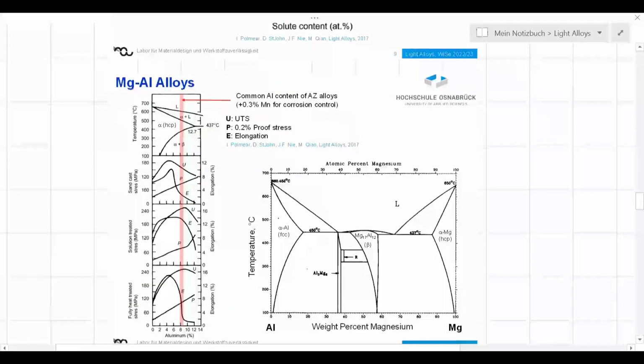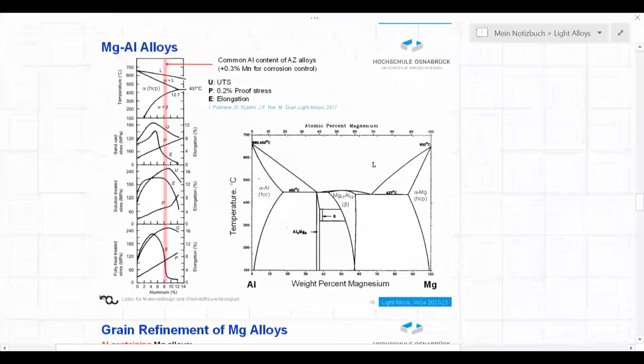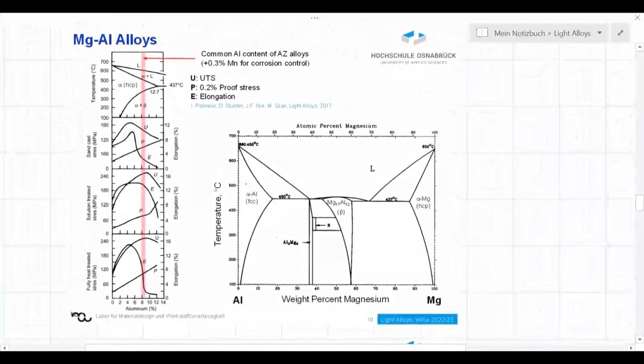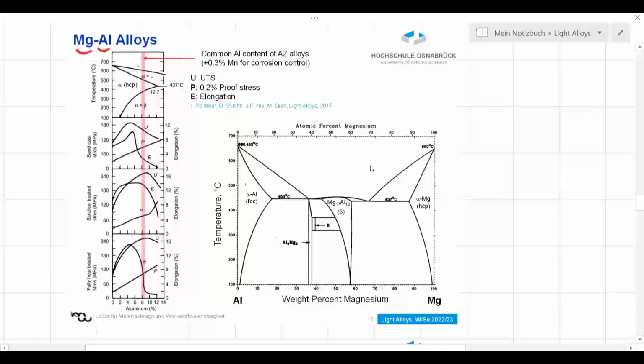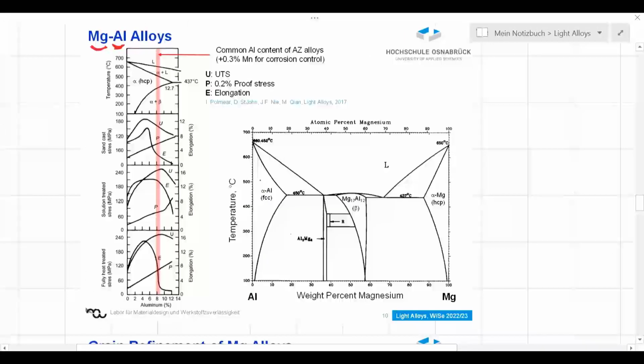Good. And we could also have a quick look at their phase diagrams. What happens if we put aluminum in magnesium? So this is the most important alloying element, aluminum. It makes magnesium alloys somewhat heavier, but still, it's a better situation than when you're putting a heavier element like zinc or manganese in magnesium alloys. They are metals which are heavier, and aluminum would be a good option, right? So I could think about aluminum as not increasing the density of magnesium alloys dramatically.